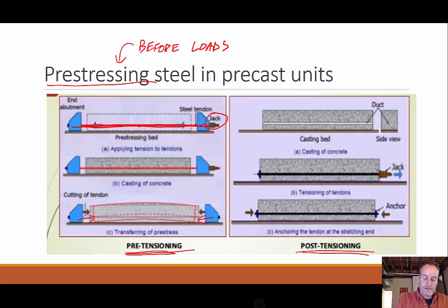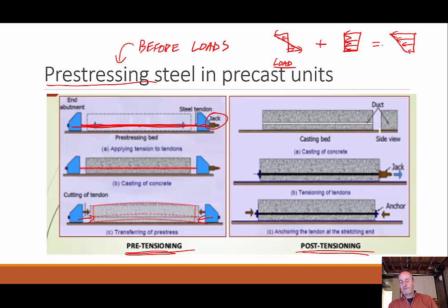And in essence, what you'll end up with is we have our initial, from the load, we have our concrete profile for stress and strain. Well, what this is doing, it says, well, now we're just going to put the whole thing in compression due to this pre-tensioning or post-tensioning. Well, I can add those two together. And if I add them together, I end up with something where the top is way more compressed, but in essence, the whole beam is in compression through its profile. So we don't have a tension region because it's sucking the whole thing together. That's a little bit more than what we really need to know, but that's kind of background information between this pre-stressing and post-tensioning.